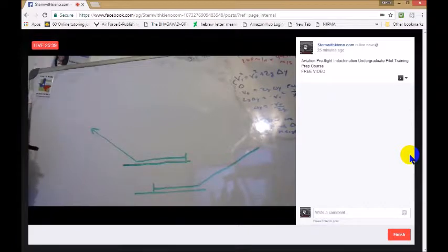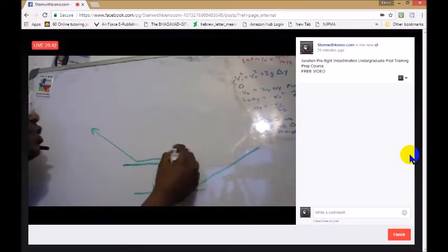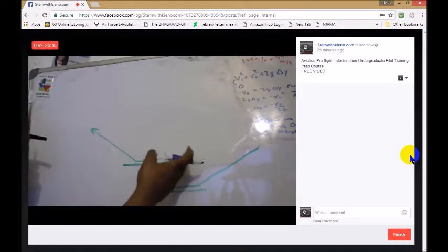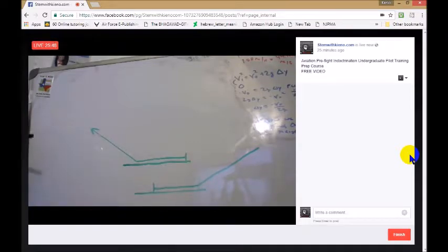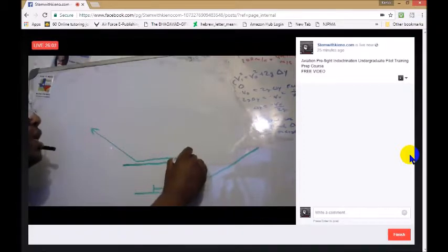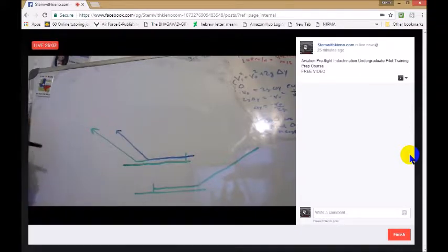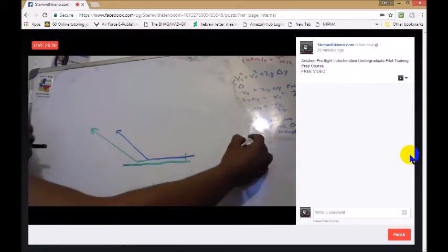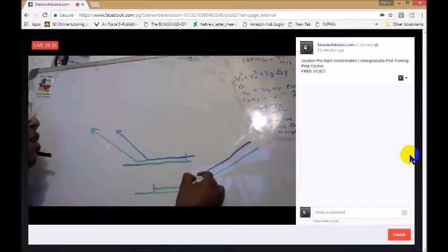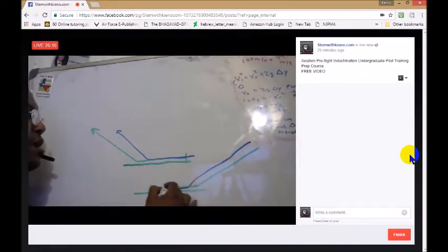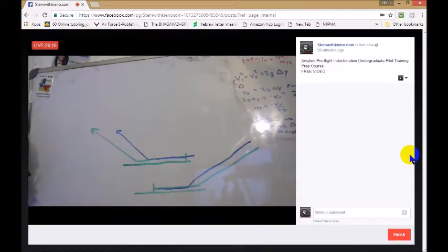All right. Well, if we are a smaller aircraft, then what we need to do is, if the air traffic controller clears you for takeoff, he or she will say, November 310 Delta, you're clear for takeoff, runway 27, caution, wake turbulence. That is the phrase. Caution, wake turbulence. They will say that over the frequency. So what you would want to do is you would want to take off before the departure point and stay above and upwind. Conversely, if you're landing, you want to stay above the flight path of the aircraft and touch down past the touchdown point of the larger aircraft.